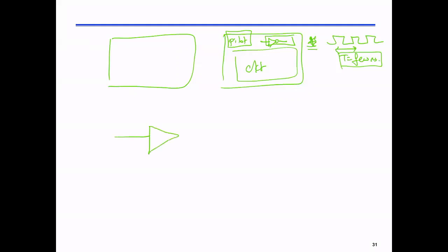Let us say that I have an inverter and the input here is 0. What is the output here? 1. Great. Now I connect this to another inverter, back to back. They are even. The one here, what does it translate to? 0. So this is a basic latch. If I store a 0 here, it will stay there forever because this one will preserve it, right? One will carry the 0 and the 0 will carry a 1. So this is a basic latch.